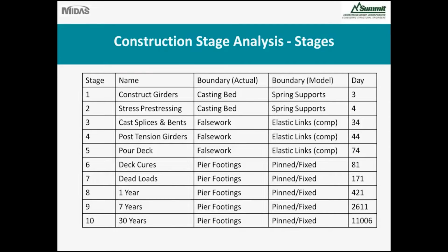The alternative option here is to use vertical restraints, run the model, and analyze whether or not the restraint was restraining the girder in a downward direction, and then rerunning the model and releasing any of those that were restraining the girder downward. Shoring towers won't ever hold a girder to the ground. It can only keep it from deflecting. And then once we get into the deck curing, it's just the pin to fix connection of the piers.